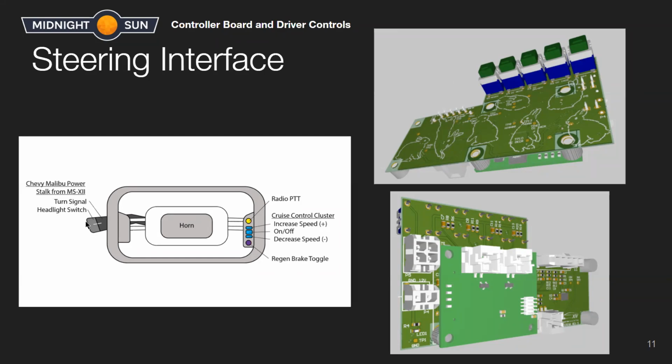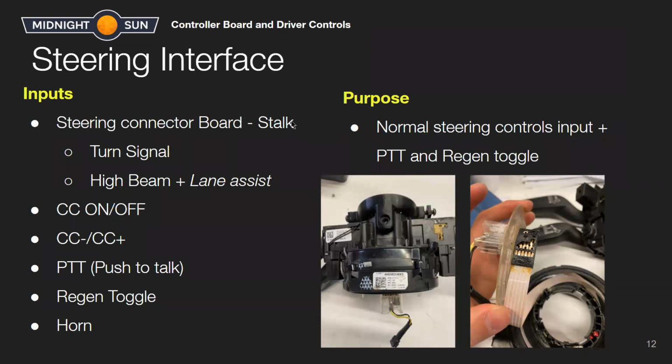In a normal car, you have to put on your indicators when you're turning, and that's essential. It's not a button, it's usually the stock that you can toggle. And so with the stock we buy off the shelf, we have a board that fits into a slot in the stock, and it'll provide us the analog references for everything from the stock. This board literally just sits inside that slot, has a connector, and connects through to the steering main board, which will provide its input paths. So with that, we could really talk about the inputs a bit more.